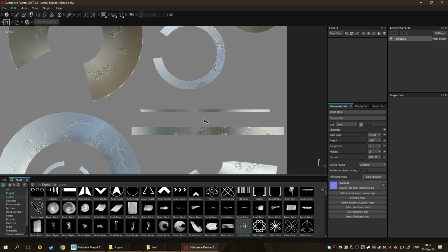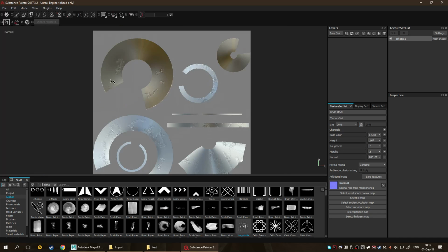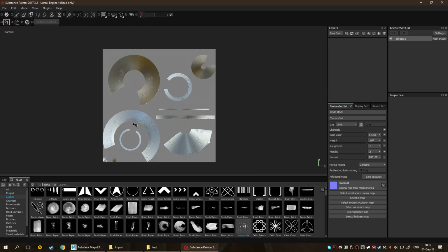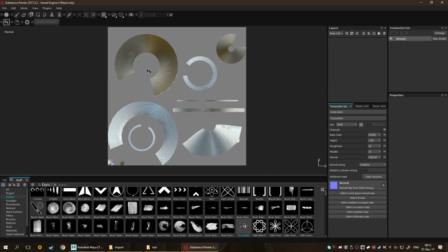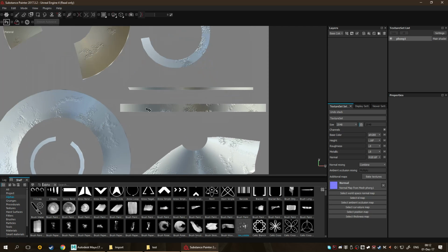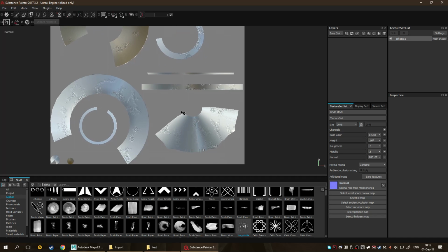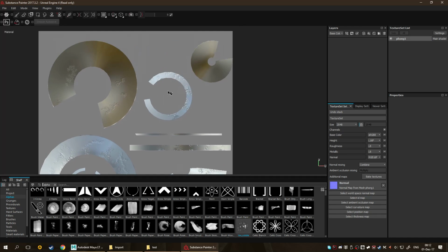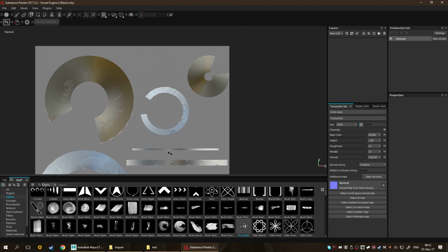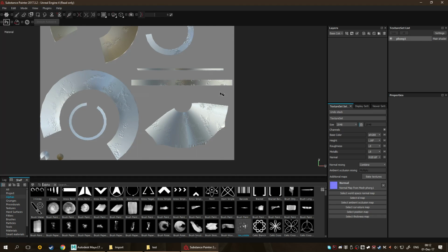What we did here, by the way, is not ideal, because I cut these apart, but I didn't really straighten them out. So I'm not using the full capability of my UV set here, because look at how much texture space I'm simply wasting. And the reason to straighten these out is only in order to save space, right? You could grab these and put them down over here, for example, and if you straighten all of these out, you could probably fit everything in here in a small square like that.